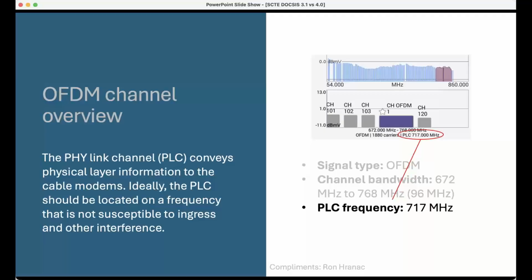So what I do is I can just turn off the subcarriers that are being impacted by that RF impairment from LTE. LTE's used by our cellular phones to talk to the tower. So if I turn them off, just the subcarriers that are being impacted, all the other subcarriers will still transmit data to the cable modem without any problem.